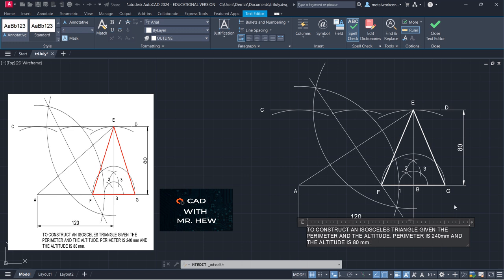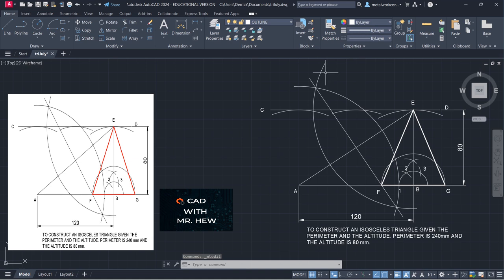All right, so what we can do next, we can break this arc. It's too long, right? So go modify, break. So we click on this arc and then we click here, press enter. We click on this now, we can delete it, right? So this brings us to the end of today's video. In today's video, we looked at the construction of the isosceles triangle given the perimeter and the altitude. Please take care until we meet again. Bye.